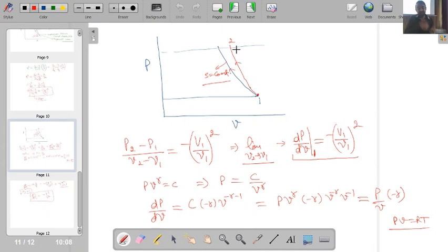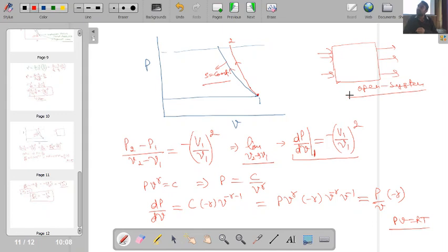And mathematically this is clearly evident because this compression process can be equated to a control volume approach. Say this is a control volume, some fluid is entering over here. Either you use a compressor or a shock wave. At the exit of this, you will have mass leaving at higher pressure and lower specific volume conditions. Okay, so this is nothing but an open system.